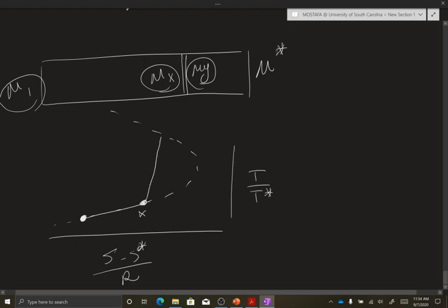Then the normal shock moves you to the upper line, which is the subsonic line. This is the star condition, right? If I ask you to draw this, you have to find all of these values, so it shouldn't be an approximation. So 1, X, and then after the shock, you are on the subsonic line, and then it will get you to the star condition at the outlet.